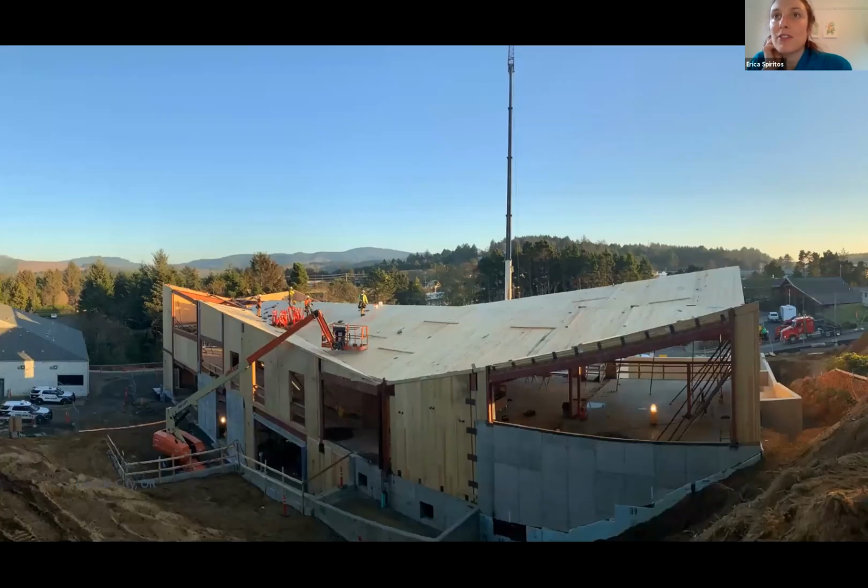Sometimes these buildings call for double height steel columns, and so we want to be thoughtful about erection aids that can get in the way of placing CLT panels. Lots of little things like that can trip us up in the field. And then this is another steel hybrid project, which really was challenging for us. So we'll just end on a challenging note.